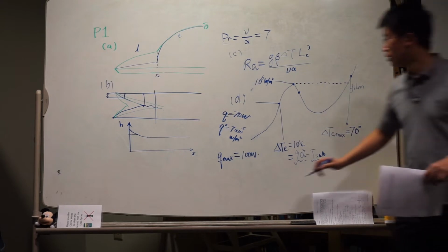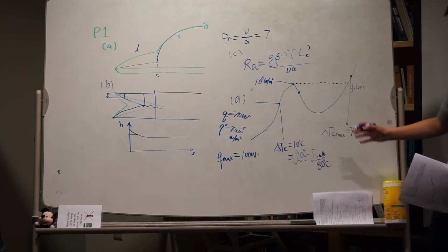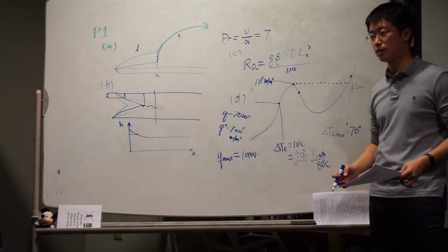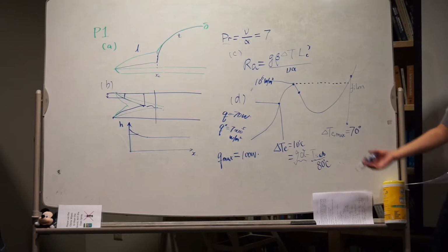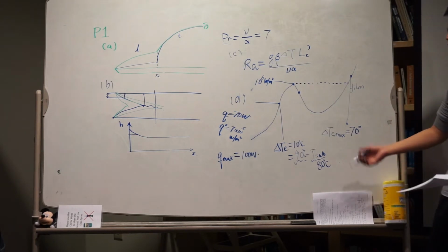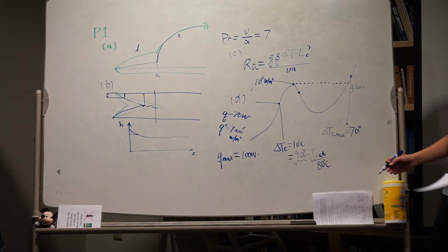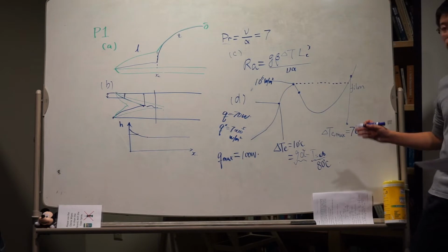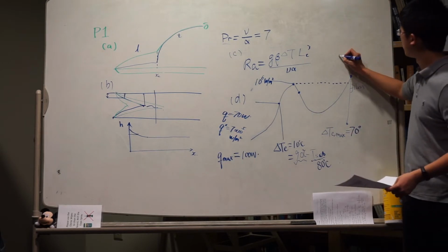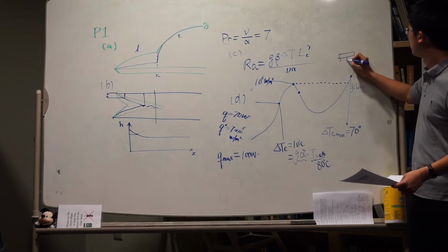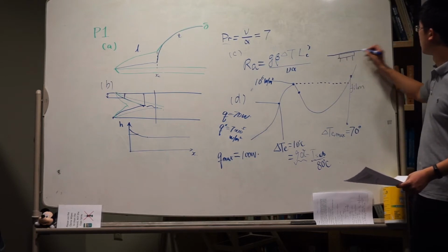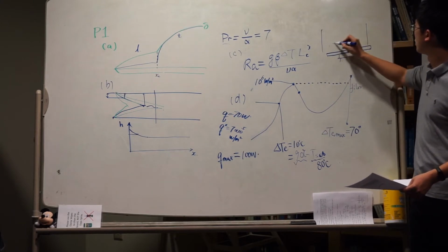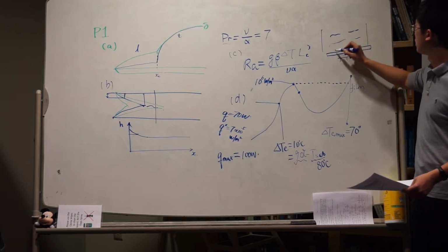So for those cases, one thing is to make a smarter electrical design to reduce the power consumption. The other one is to extend the surface, so we are not limited by that area, maybe by putting some fins, or simply extending the surface. Let's say this is the chip, and you just put a large metal plate on the top, right? And this is immersed in the fluid. Some boiling is happening.